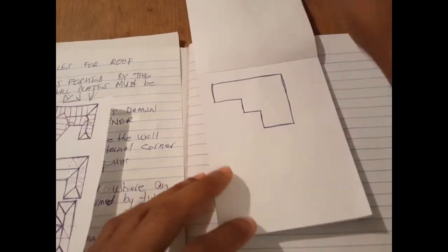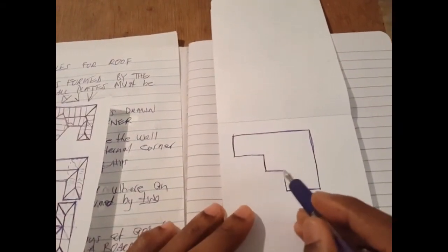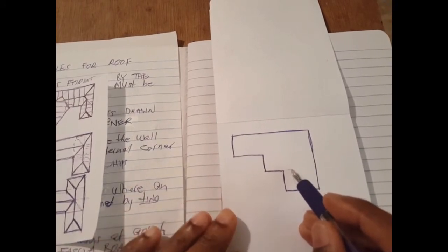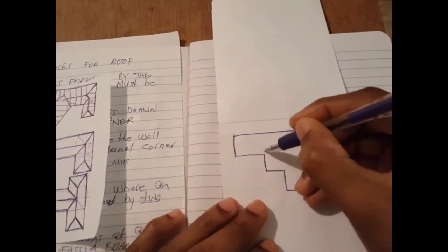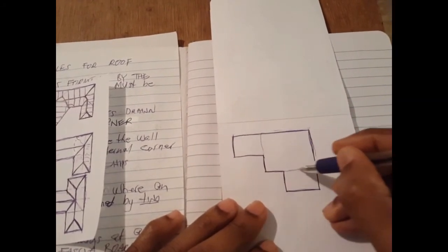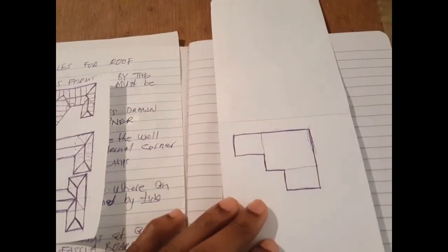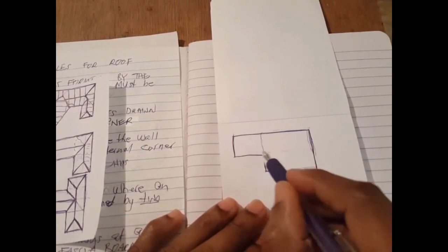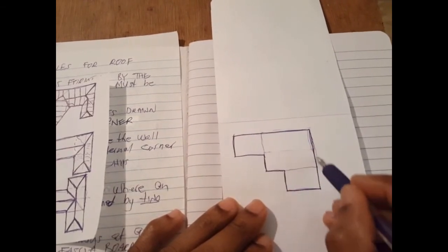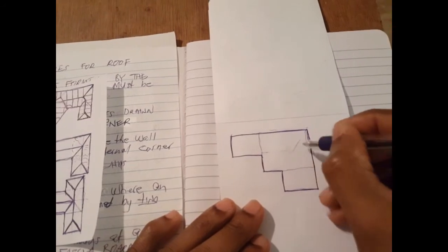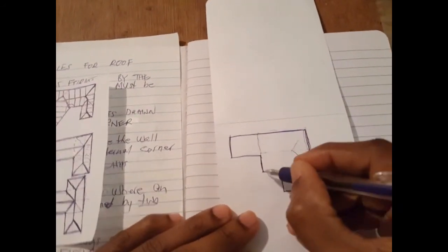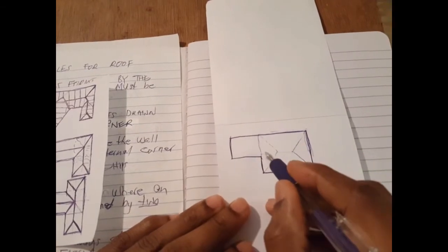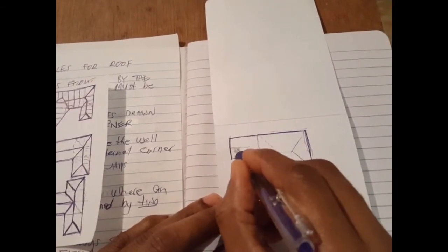Let us look at this one now. This one is a little bit more complex. The rule says that we are to draw the largest possible rectangle first, and then the smaller one. So here, from this point, we can get the largest possible rectangle. That's one rule. The other rule states that we must draw the ridge along the longer side in the middle. So first, I create this imaginary rectangle. Then I draw this at 45, this at 45 degrees, this at 45, that's at 45 degrees also. Oh, before that, I probably should have drawn my ridge line first.